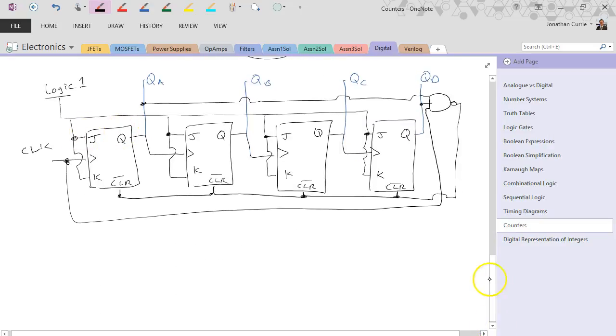As we expect, just like we've seen in the previous example, this all clocks through, providing a counting pattern. But let's have a look at this AND gate: when this is a 1 and this is a 1, those could be 0. Remembering this is the most significant bit, 1, 0, 0, 1 equals 9 decimal. And we get a clock pulse, rising edge, all counters reset.